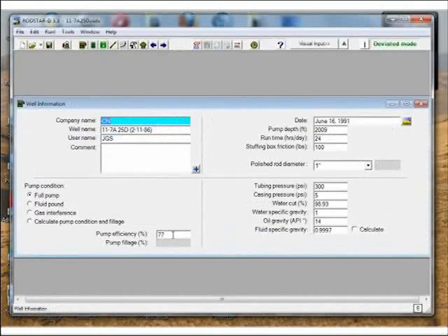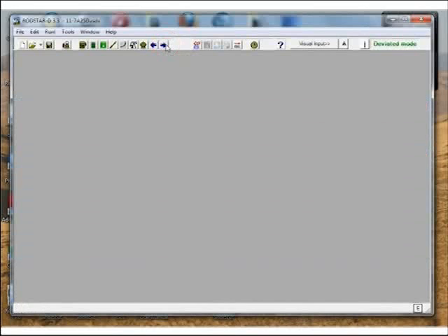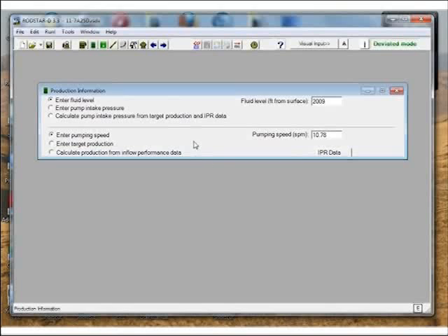In other words, how much production can the system make. But another thing I need to change is my pump efficiency. I'm going to use 95% efficiency because, remember, that affects the loads for these types of wells, and you want to calculate a design with the highest loads to make sure that the rods or gearbox will not be overloaded, or the structure of the unit.